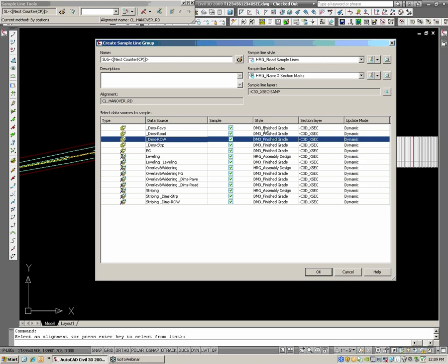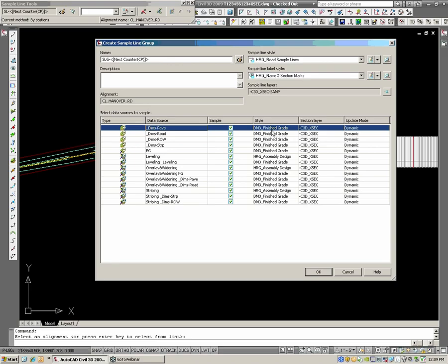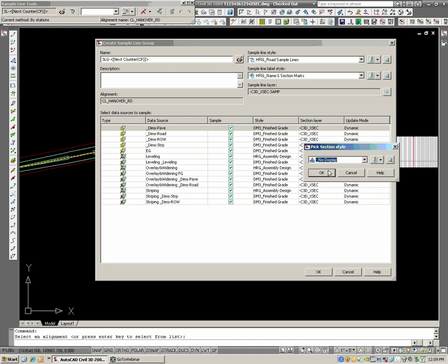Now, that's okay because you really wouldn't see it, because it's going to line up right with the top of your cross-section. But that adds to stuff that needs to regenerate, and slowness. This is where I find people get into trouble with Civil 3D a lot when they're talking about slowness. You have to pay attention and not show all these surfaces. There's no need for it, and that's a lot of stuff to regen for all of these cross-sections we're going to plot. So we're going to click on each one of these and set these to no display.